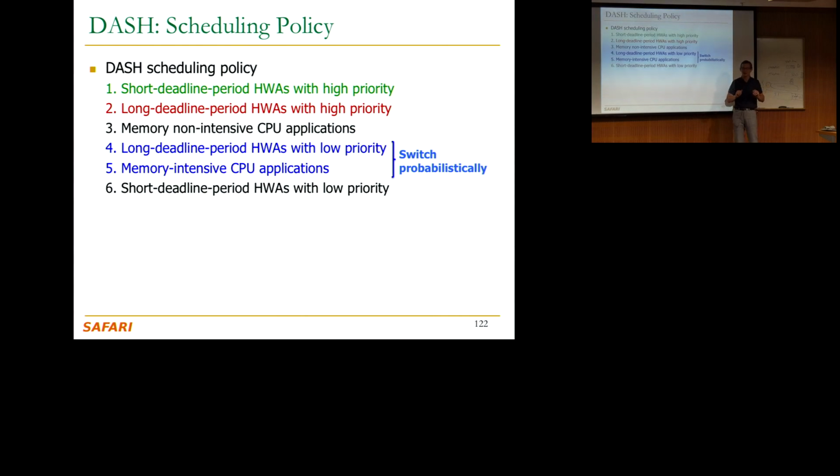That's the idea. So between 0 and t, because you've scheduled these based on the worst case requirement, you're safe. That's why you can put them at the bottom. But if it's high priority, because you've scheduled them based on the worst case requirement, and the worst case requirement is important to you, they have to be at the top. That's the idea over here.